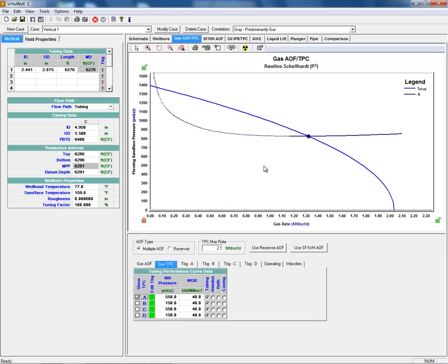We notice that the tubing performance curve has a dotted and solid portion. The transition point shows whether we are operating above or below the critical rate required to lift the liquid in this well. We can see that we are currently operating above the critical rate. However, we could also conclude that in the near future, we will probably begin to experience liquid loading issues.